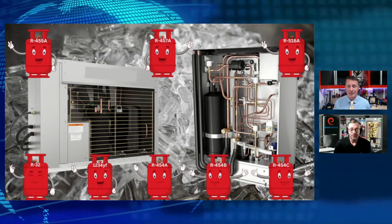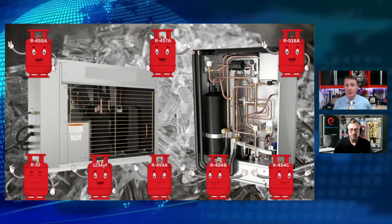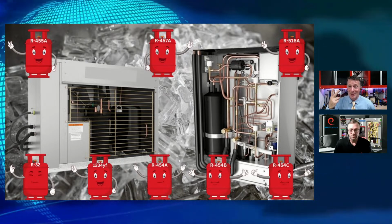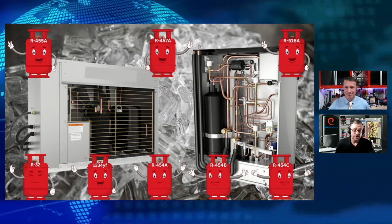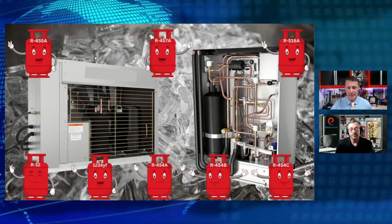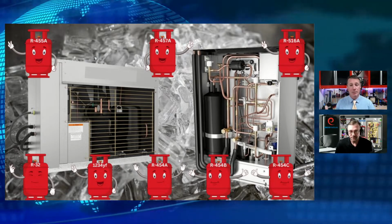So exactly. People always ask, well, why do we flip a can of R410 upside down when we're introducing it into a system? Well, because it's a blended refrigerant. It has two, R32 and R125. Any of the 400s should be charged as a liquid throttled in, and then 500s not necessarily. But the 400s for sure have to be throttled in as a liquid. Exactly. So nothing new. We just have more blended refrigerants that we need to be aware of.